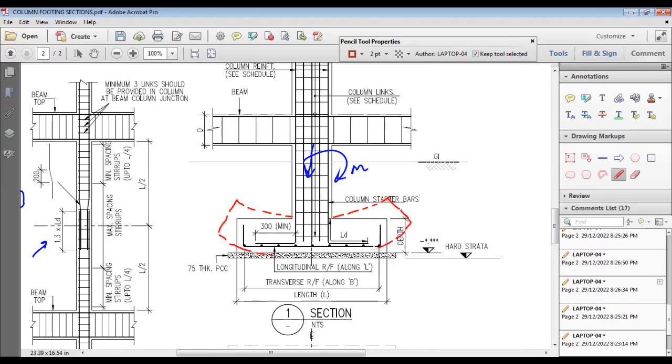Cantilever bending moment we can see. So there is tension at the bottom, and that's why you can see this black color reinforcement. Main steel is at the bottom, like cantilevers. And there is an L also for the reinforcement. And this column reinforcement is embedded into the footing like this. So that's why in footing we generally have reinforcement at the bottom, because tension is at the bottom.